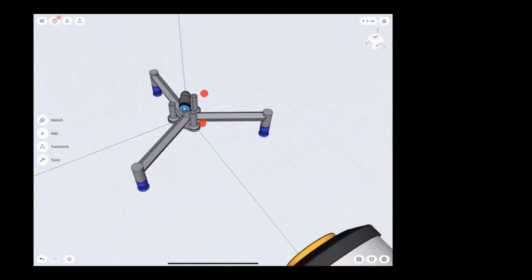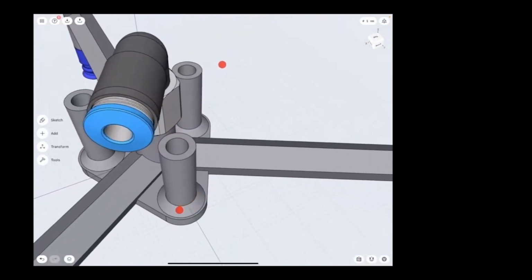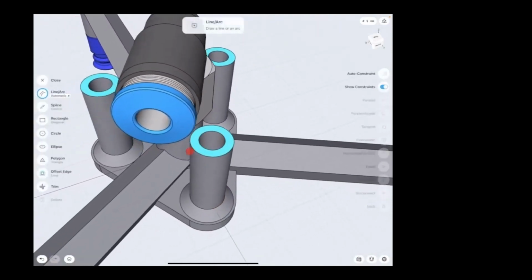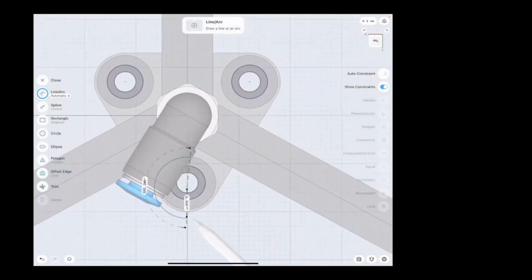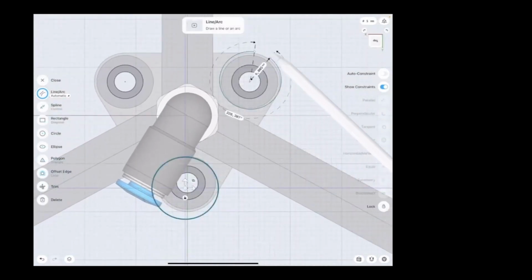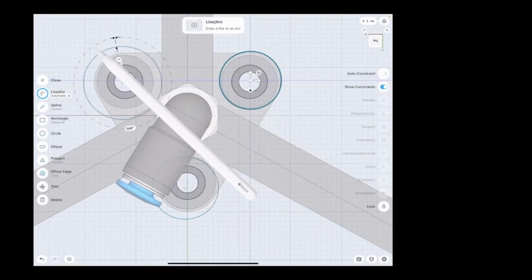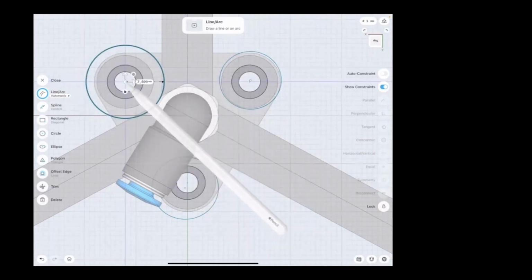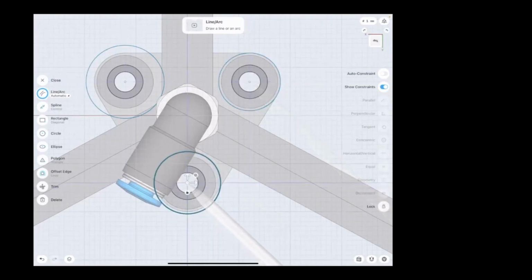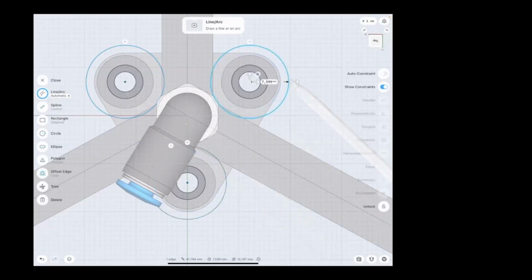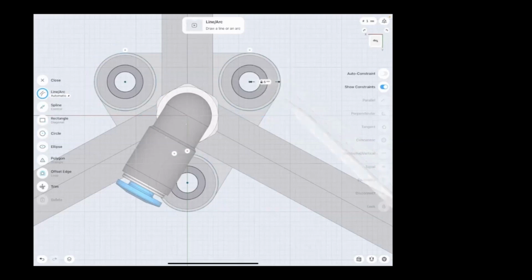I will design a bracket in the next few steps that will be placed on the top surface of the screw dome. The main shapes that define this bracket will be 3 circles placed on the exact midpoint of the screw domes. And after locking those together and constraining the radius to be equal on these 3 circles, I will set one radius to be 6 millimeter.